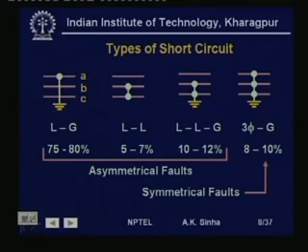So, therefore, we will look into the symmetrical faults first, because this analysis is much simpler, whereas in case of asymmetrical faults, this is a condition for unbalance, and we have to do the analysis for an unbalanced system. We will talk about this later, how we tackle the unbalanced system operation and analysis.